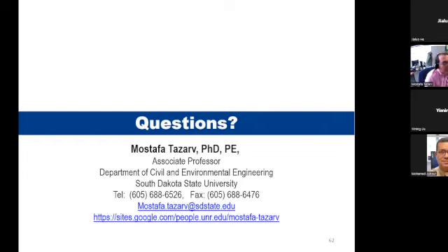No, that's actually a very good question. The crack widths, let's say after earthquake, is not a good indicator. The reason being is the crack is wider at the peak displacement of the column, and after the earthquake, the column comes back. So what you see after the earthquake is not an indicator of the big displacement. So we did not include the widths of. No, I mean the depth. No, I mean the depth of the crack itself, the penetration of the crack into the column itself.